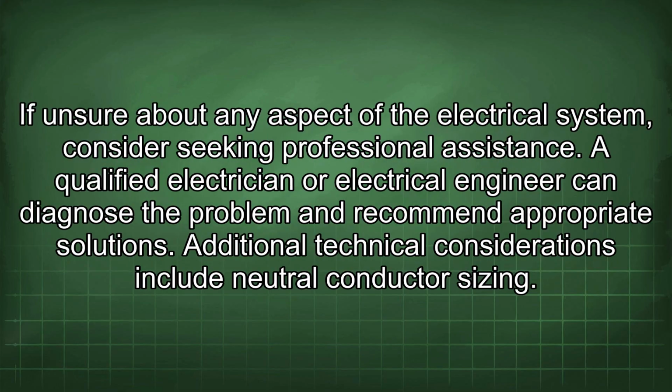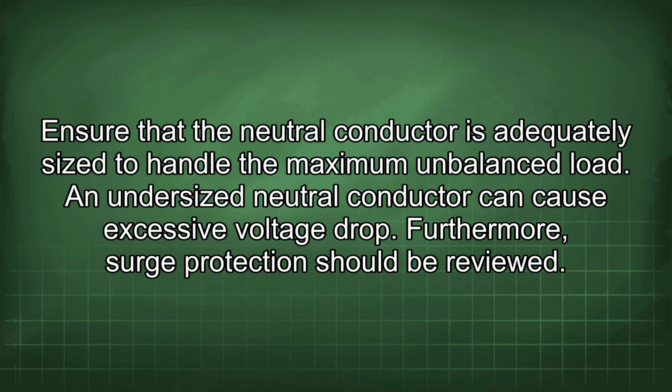If unsure about any aspect of the electrical system, consider seeking professional assistance. A qualified electrician or electrical engineer can diagnose the problem and recommend appropriate solutions. Additional technical considerations include neutral conductor sizing. Ensure that the neutral conductor is adequately sized to handle the maximum unbalanced load. An undersized neutral conductor can cause excessive voltage drop.